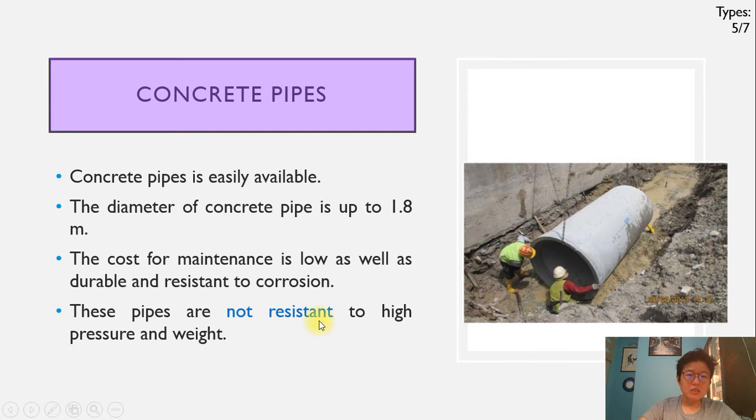However, they are not resistant to high pressure or weight. Buried, placed properly on the bedding material and covered nicely, at sufficient depth, that's fine. But if you have too much load on top, like a heavy truck or heavy traffic, you can actually break it.